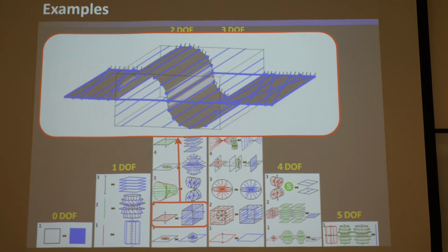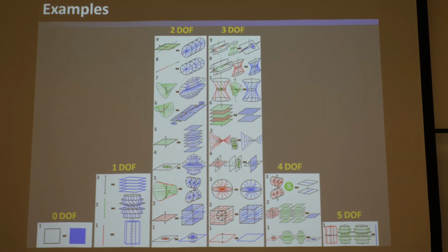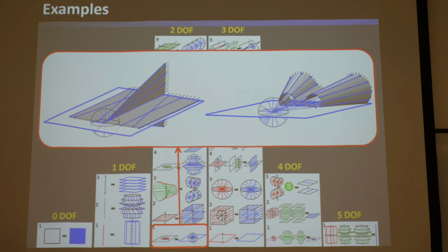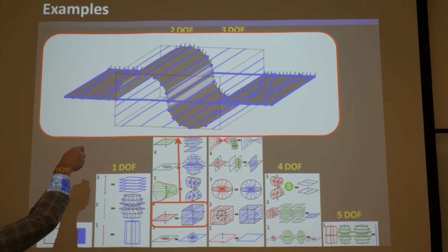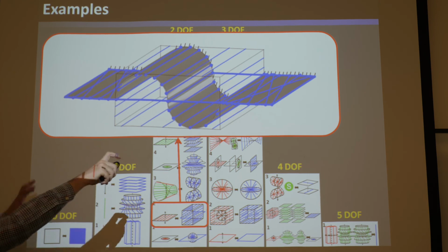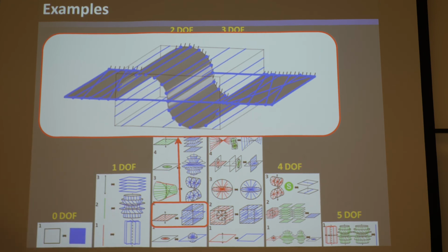Okay, and by the way, those two would have an order of constraint of 4. This one is another one where I couldn't just give you the geometry and say is this parallel or serial, because if you joined this edge over here to a body and then this edge to a rigid body, it would not be a parallel element, it would be a serial element. It wouldn't satisfy the condition. You couldn't find any blue lines that satisfy those conditions.